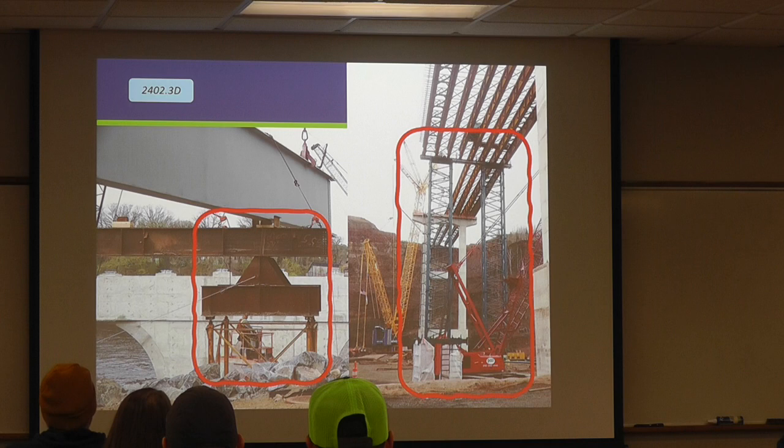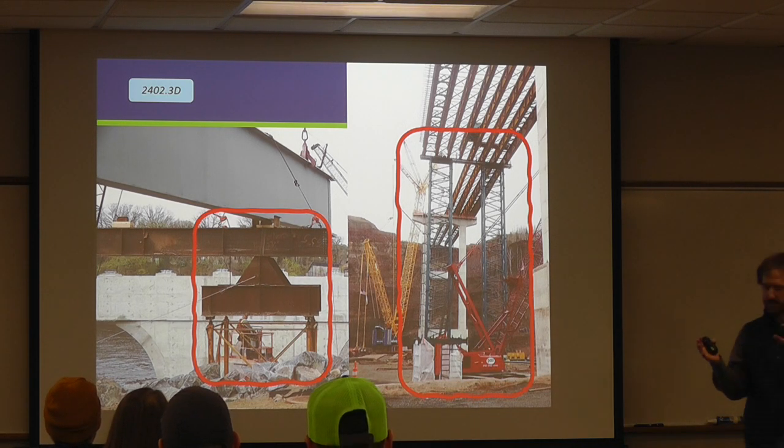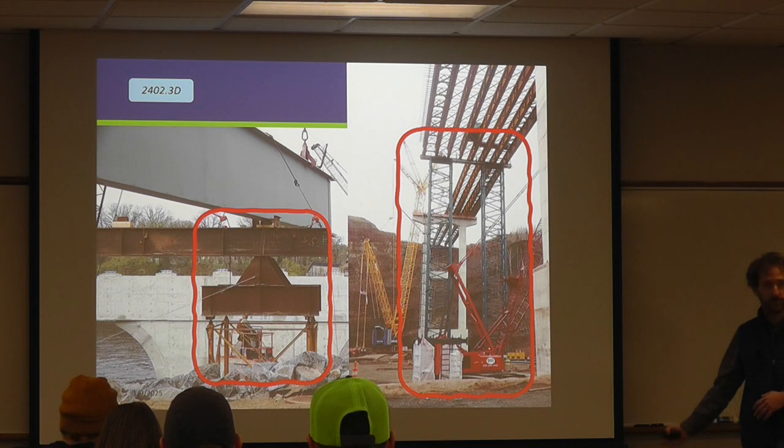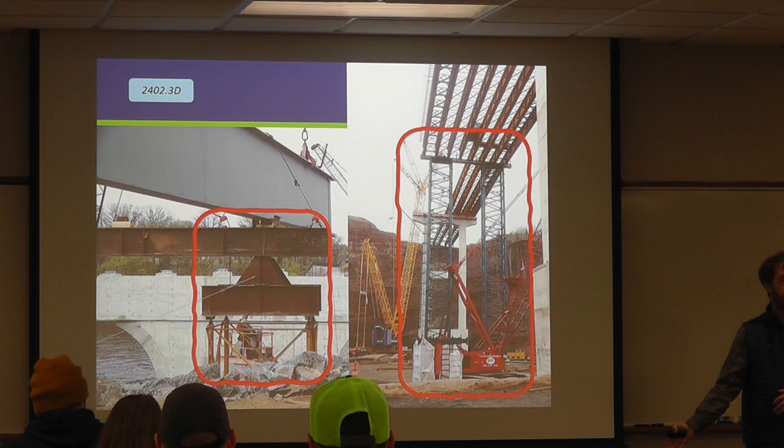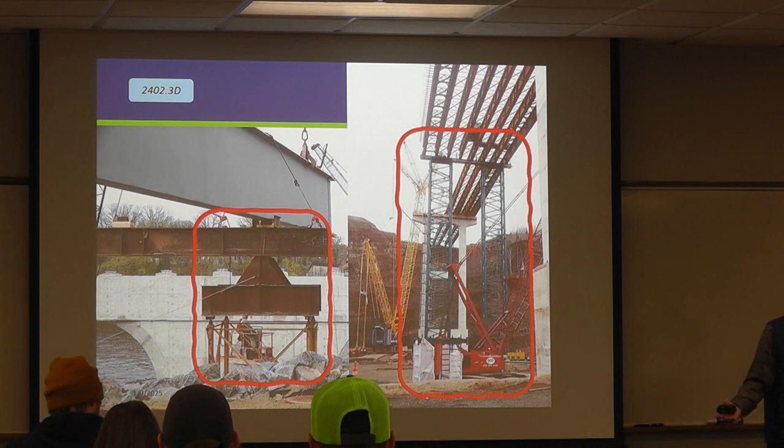And I don't see the photo coming up here, but I know it was roughly 10 years ago, there was a shoring tower system down in Illinois, and I believe what ended up happening is the contractor brought out the wrong capacity shoring. Called for 100 ton, they brought out an 80 ton, something like that. Very light breeze outside of the work shifts. Unfortunately, nobody was on the site at the time. Caused the whole system to fall off and end up on the ground. Right? It's catastrophic to your project. Obviously, get a big chunk of steel landed on somebody, it's going to be catastrophic for them, right?